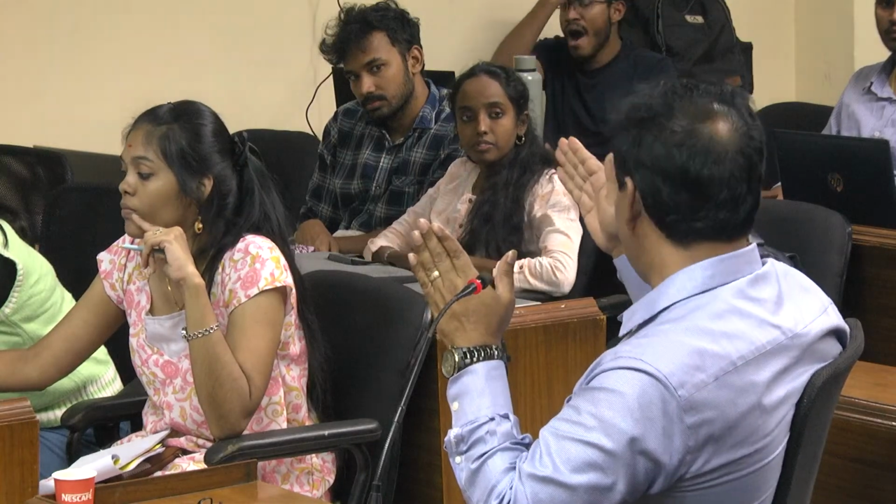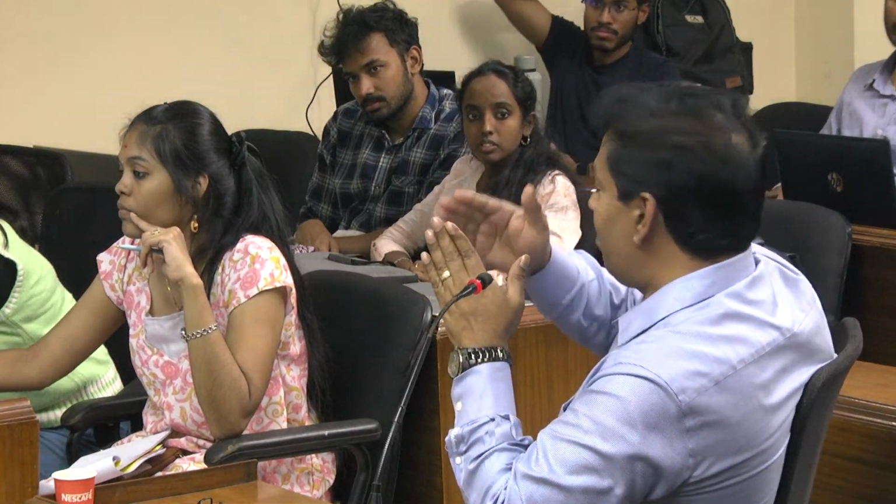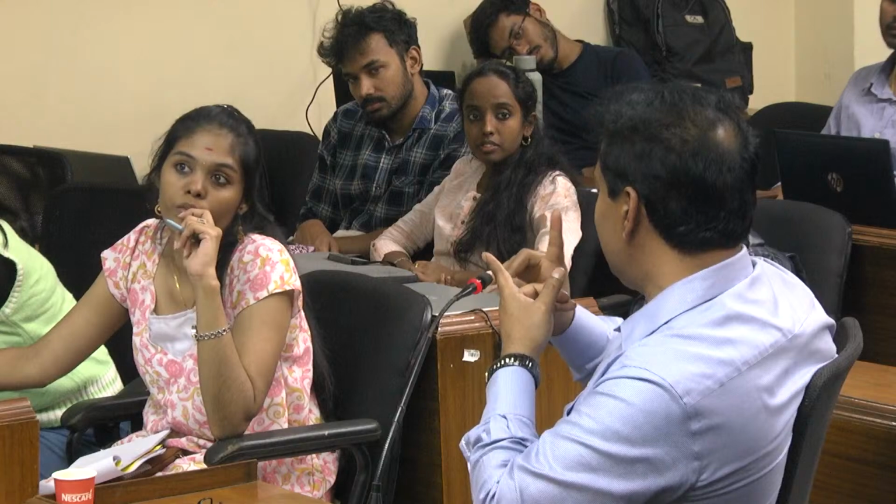Just see what your total time is and what your time step size is, and then you can calculate after how many time steps you want to save the data. Save more, not a problem. So it helps in two ways, three ways.